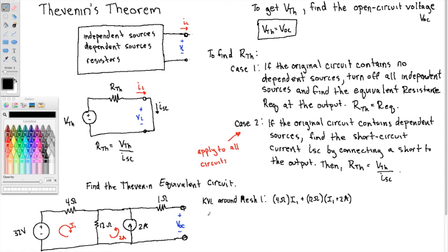I increased by 32, so I need a minus 32 volts there, equals 0. Okay, combining like terms, I have 16 ohms I1, and then I've got 24 volts and minus 32, so that makes 8 volts when I add it to the other side. So that implies that I1 is 1/2 of an amp.